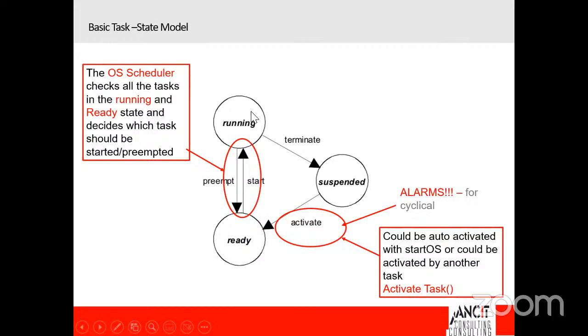And as and when it is modifying the data, let us say, for example, the variable is right now present in your CPU register, and this runnable is being preempted. As it is being preempted by another higher priority runnable, that runnable will execute, and that variable will now be stored back into the memory location, when I say memory, RAM. Now after this preemption, the older runnable which was executing will start executing, and now it will replace it with a new value. So instead of getting one value, it now gets two values. So this is typically what we call